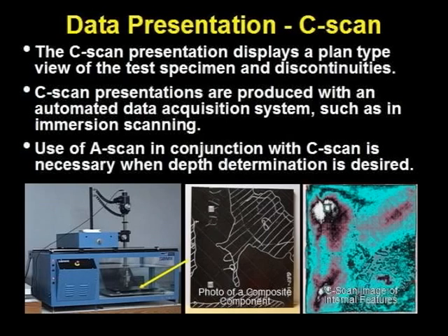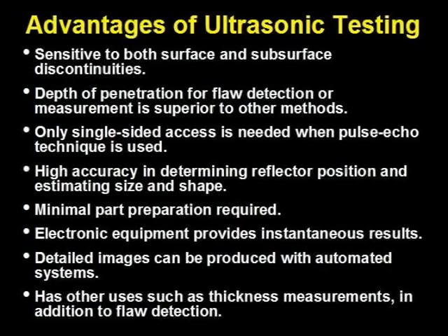on the test article. The transducer is held by a search tube whose X, Y, and Z coordinates may be automatically controlled. The longitude and latitude of the transducer may also be adjustable. Furthermore, the test article may be placed on a turntable. Thus, up to 6 degrees of freedom may be used to generate a scan which follows the geometry of the test article. Ultrasonic testing has many advantages for non-destructive testing.